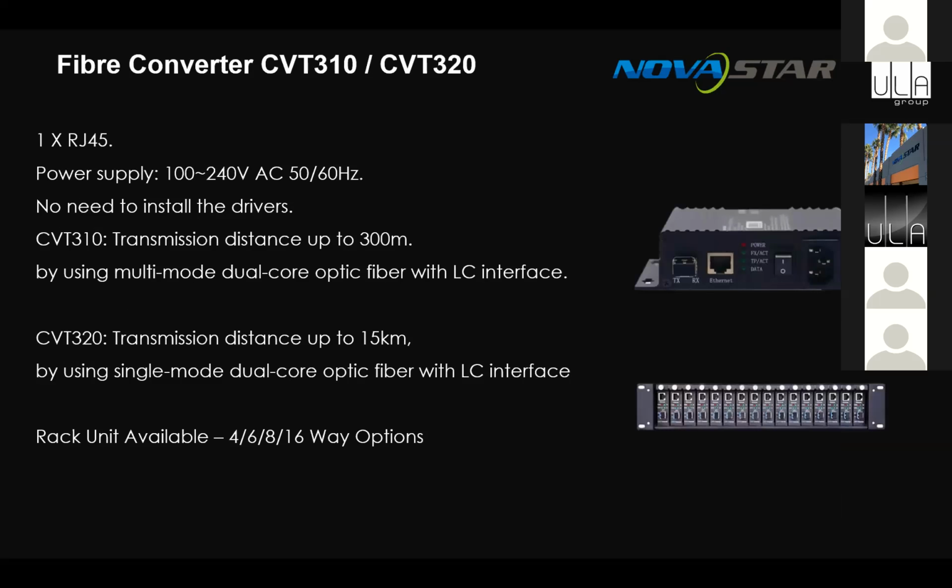One of the other little boxes that we've got, I did touch on it yesterday talking about the fiber extensions. You need to be cautious with what you use for Nova screens. These are obviously the Nova certified boxes. There are some other aftermarket ones that will do it. Just bear in mind, while it's saying it's Ethernet, it's not IP Ethernet. And a lot of the fiber converter boxes out there will treat this data as IP data, try and convert it and spit it out, and it won't work.